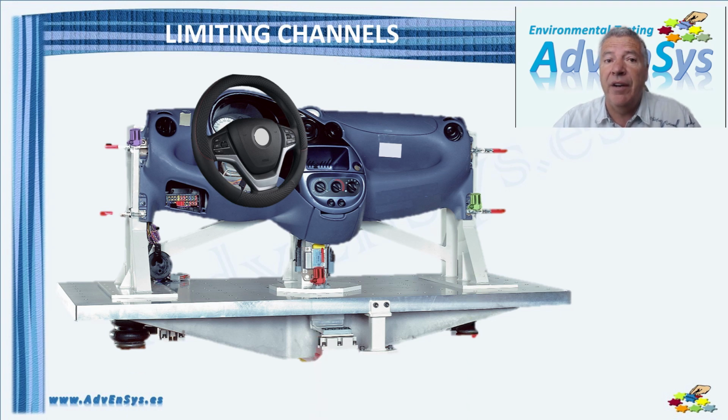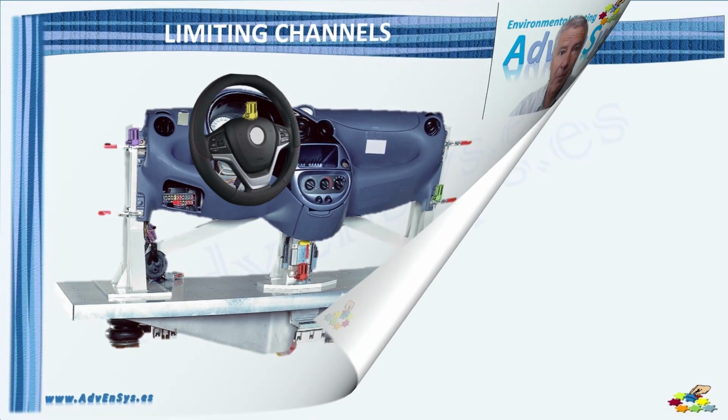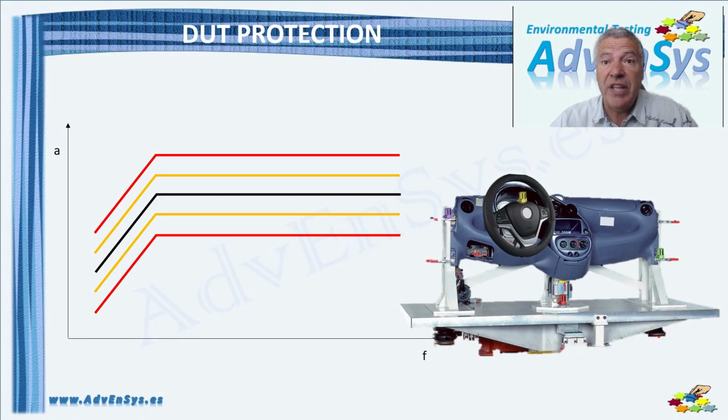We will place three accelerometers close to fixing points for test control. We also install a monitor channel on the steering wheel that we will define as limit channel. In the image, we see an animation of how this channel works in a sine test. When we are sweeping up, we see the evolution of the control channels with an average control strategy in blue that gives more accurate control.